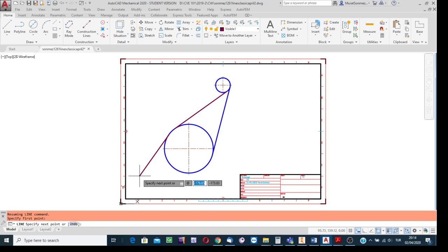Write the length of the line. If you know the length of the line, write it. If not, then for having a further extension, to trim the further extension thereafter, write a bigger number into the box, making a guess. But say that in this example, the length of the line I know, say, is 70. Write 70. And then, into the other box, write the inclination angle.